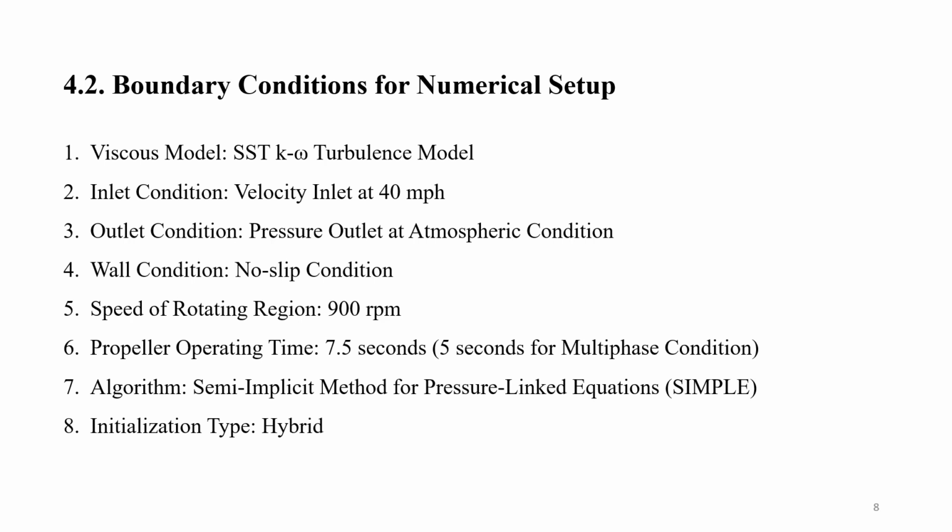In the undertaking analysis, a pressure-based transient simulation has been executed focusing on the first three-blade propeller. The simulation involves the application of essential boundary conditions to model the dynamic behavior of the fluid around the propeller over time. The choice of a pressure-based approach implies that the solver is solving for pressure, and subsequent velocity fields are updated to enhance the accuracy of the simulation.